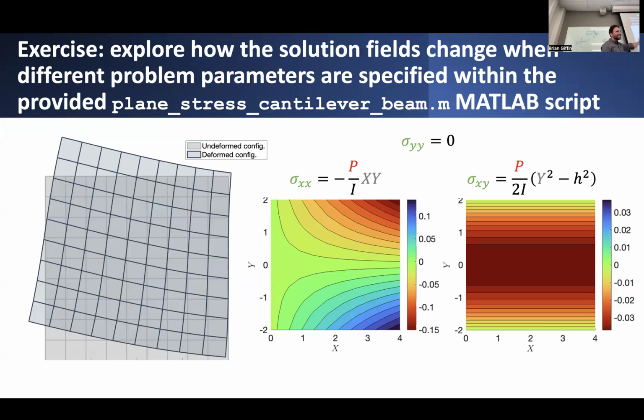In which case you see some combination of things. You see bending going on, certainly as you would in a classical beam, but you also see just straight up shear deformations. It's bending, but it's also just shearing. And that extra term that accounted for the extra amount of deflection beyond PL cubed over 3EI is actually due to that shear deformation occurring. So all these things can be accounted for just by going through our theory of elasticity, constructing these very general solutions.